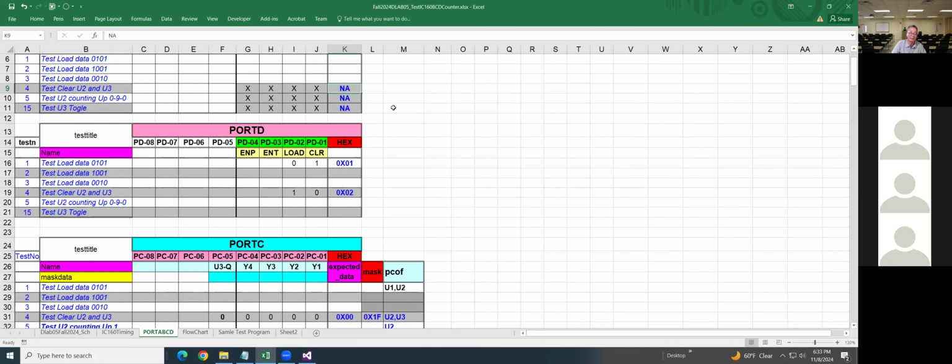Okay. The thing is, you say clear active low. So when clear active low, then load can be 1 or 0, doesn't matter. You can write whatever you want, but it not make sense. You know, zero clear is the highest priority. I get it. Okay.